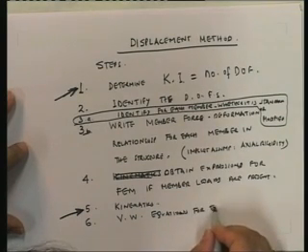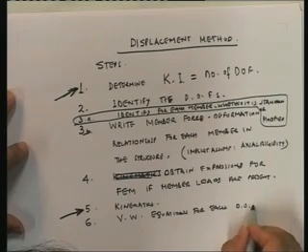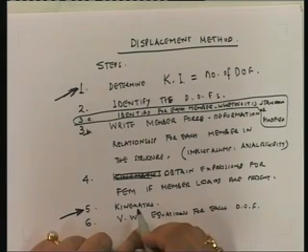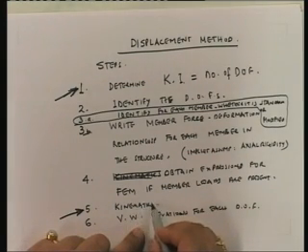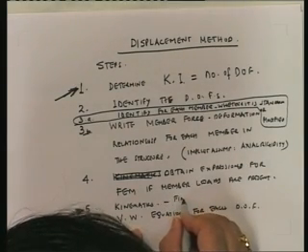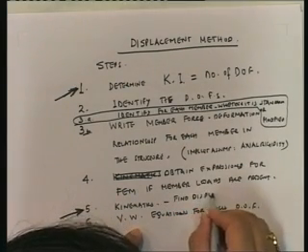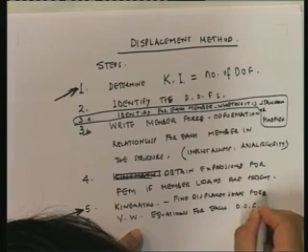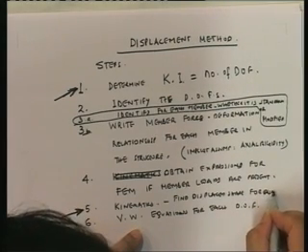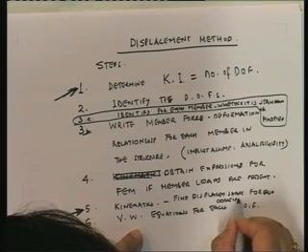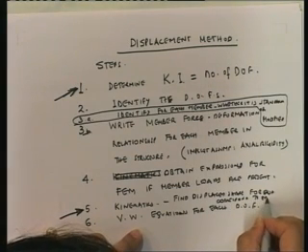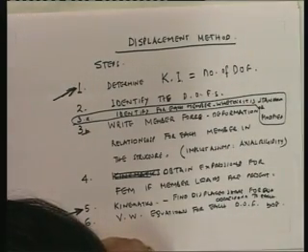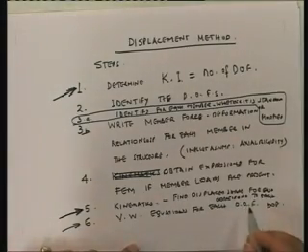for each degree of freedom. How do we go about it? We take kinematics. For each degree of freedom, we find out the displaced shape, and that is the kinematics. Find displaced shape for displacement corresponding to each degree of freedom. The next important step is the virtual work equations for each degree of freedom.